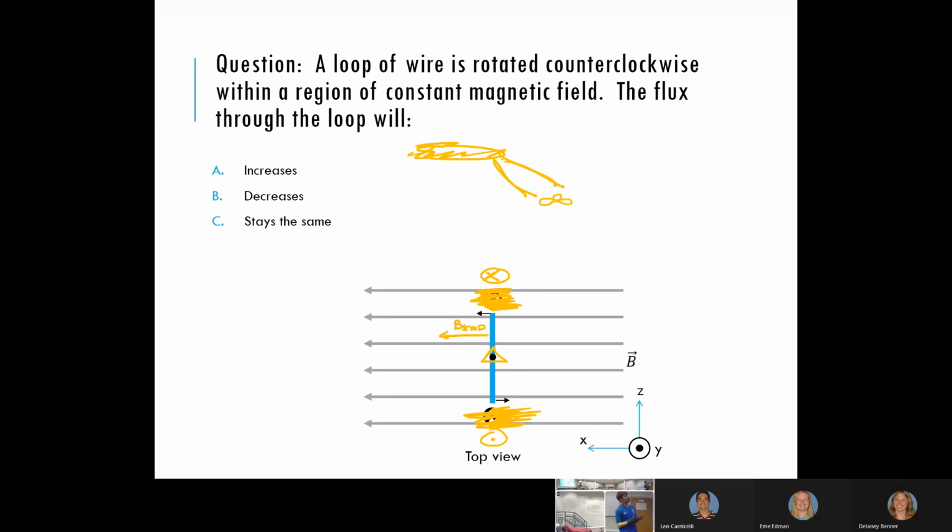So essentially it's like a fan blade attached to a shaft. Water hits the turbine, spins the fan blade. Guess what's on the other side of the shaft? Let's put a coil of wire. Take a coil of wire, put it between a magnetic field. Let's put a horseshoe magnet in here, something like this. So as water hits the turbine, it spins. That spins the shaft, which spins the coil in the magnetic field. Boom, there's your electricity. Of course, the coil wants to slow down, so you have to continually dump more water.